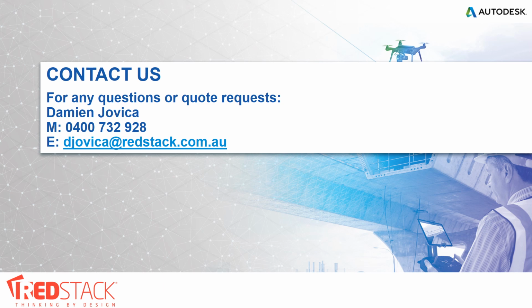The invite mentioned using UAV imagery. That invite was misleading to you, Paul Spence. I do apologize. How can this be used with ReCap? Just like those bubble views with those photos, that's how it would be used with ReCap. If you had a UAV and you scanned a bunch of photos, you could stitch them together into a 3D environment and then bring that into ReCap. Once it's in ReCap, you can then save it as an RCP file and then bring that into your CAD file or Navisworks, Paul.